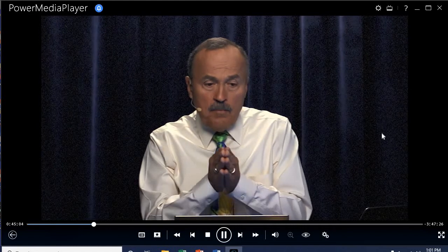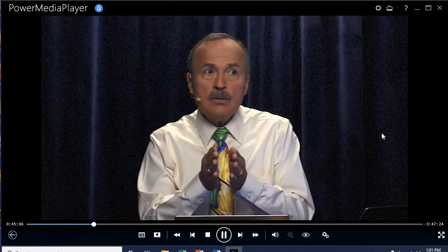But Scott, what you said, the effective ground fault current path is everything. We fail by having an equipment grounding conductor that has not made a connection, like that young boy that's swimming in that pool. Everything else we've done doesn't matter. Yeah, you strapped it within 3 feet, right? Yeah, you made sure you had a 1/4-inch gap when you put that on an outside wall. You did all these mechanical things, and you forgot to put the pressure connector, which is a wire nut, another one, under that one wire, and then you killed somebody.